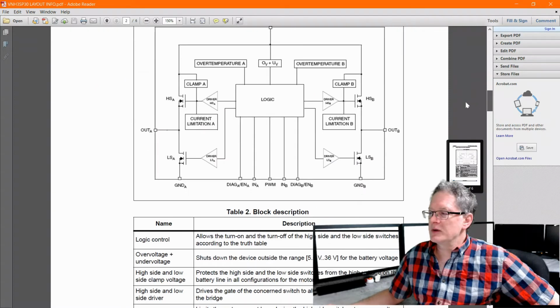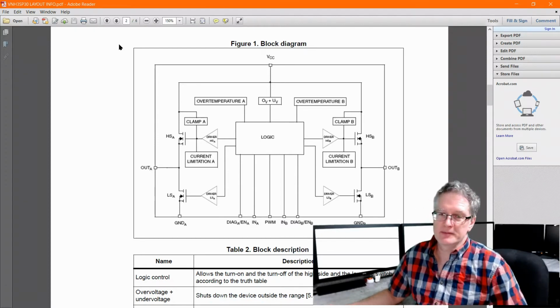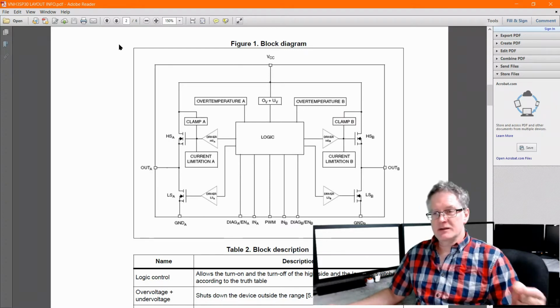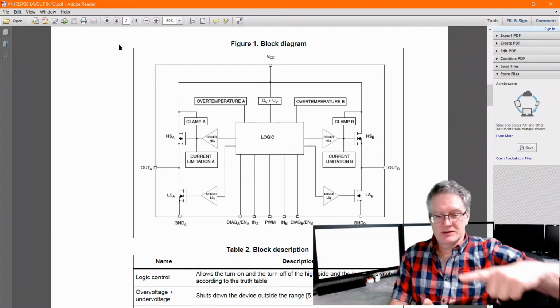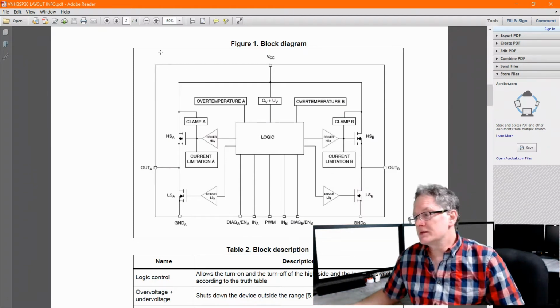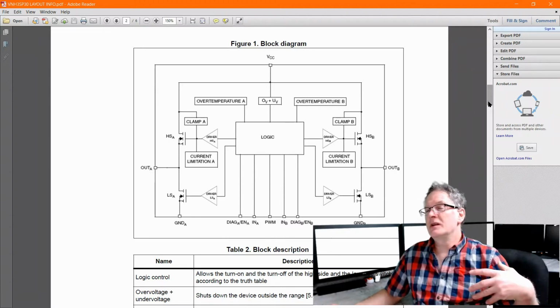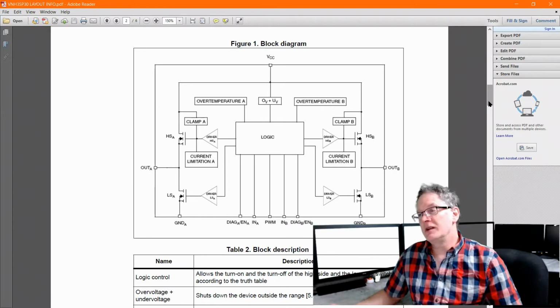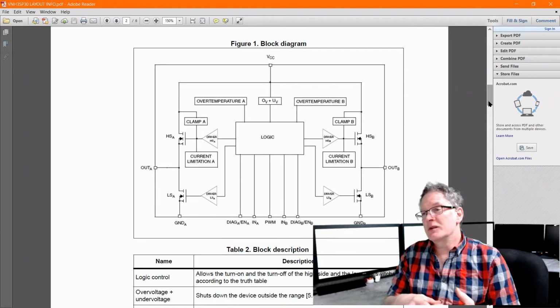And the other thing that's interesting about it is that it has a schematic symbol that has fewer pins than the footprint. And this is one of the things to remember about schematic and footprint: when you make the schematic symbol, you're looking at it from a functional view, which is a block diagram view. So a schematic symbol for most ICs is just a square with pins on the side. And it doesn't have to be one-to-one. For instance, on this schematic here, I see 1, 2, 3, 4, 5, 6, 7, 8, 9, I see 10 pins coming out of the schematic. But if you remember, there were 30 pins on the outside of this chip and 3 underneath. So the footprint has 33 pads and the schematic only has 10 connections. So they're an unequal number.